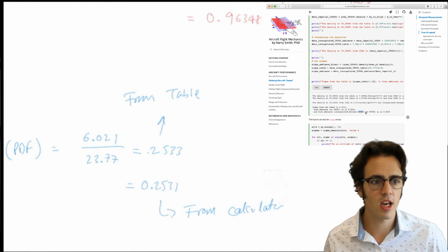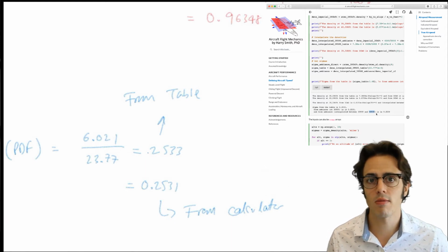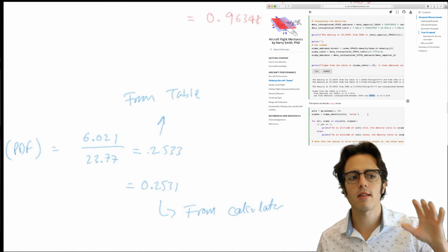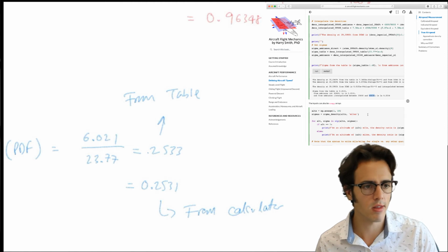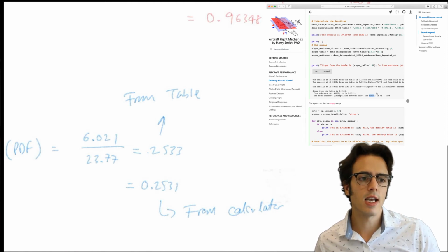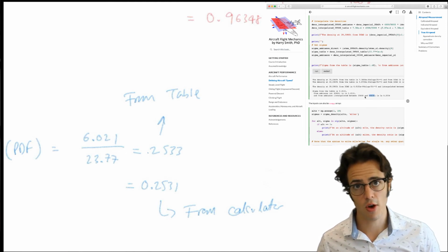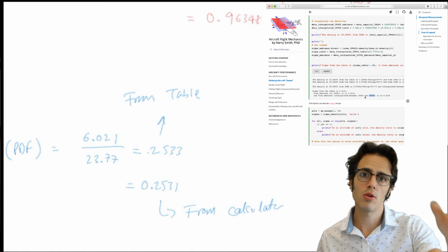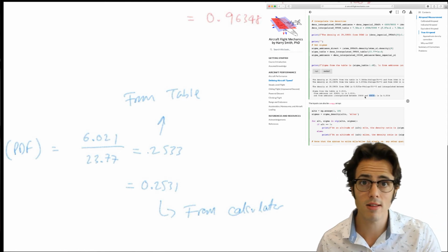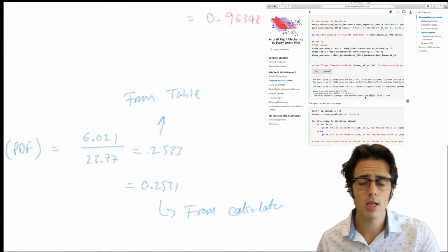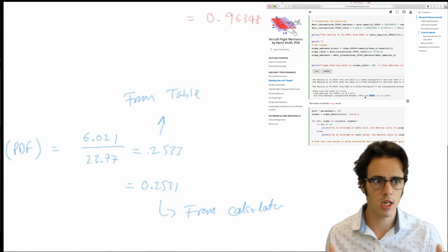If you then use 35,000 and 40,000 feet within any of those models and interpolate between them, you get a slightly different value. What this shows is that the variation of density between those altitudes is not linear, which we know anyway, and how you get those densities will slightly change your density correction factor. So for homework that I give you, use the syntax that I've written into this code to make your own density correction factor and use that. Or if you're in MATLAB, use something very similar using atmosisa. Okay, use that one.